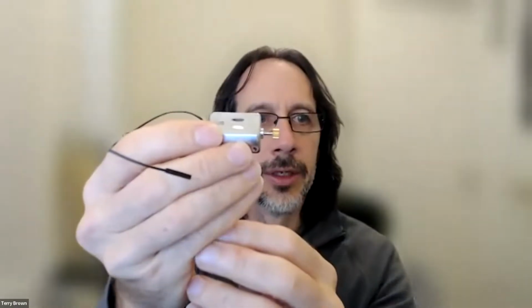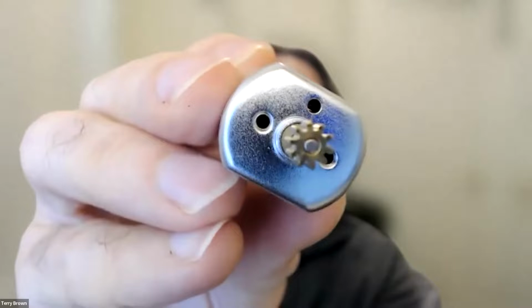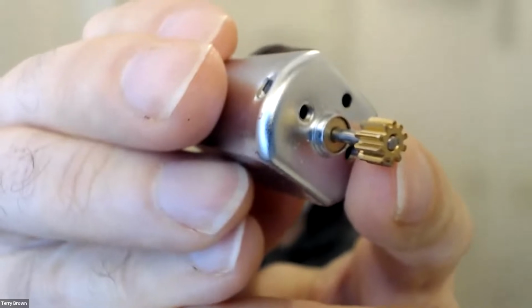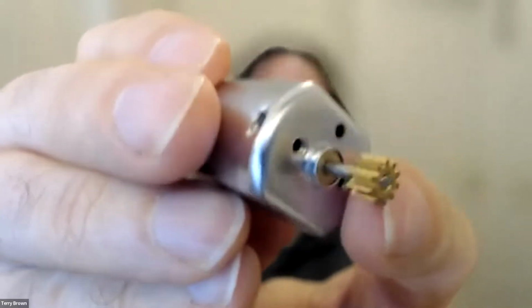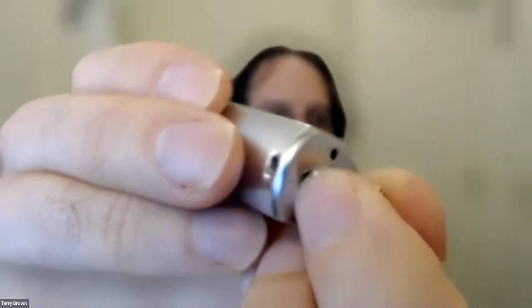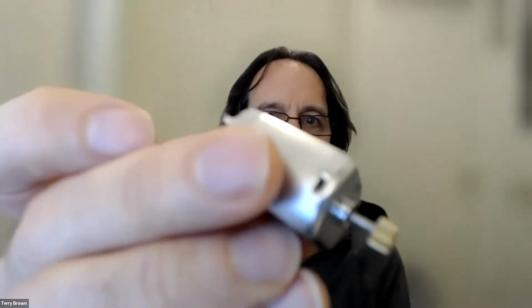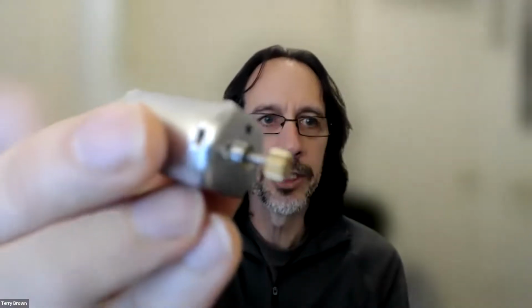And our other little one that I've got here, a little DC motor. Here you can see you've got a gear on the end. That would be attached to another gear. You'd have a contact force between the two gears, and then that would generate your torque. Because this is a DC motor, I can spin this. So if I actually spin this, you should know if I connected this up to a resistive load, then this is going to generate some power. So you can use the motor in reverse as a generator.